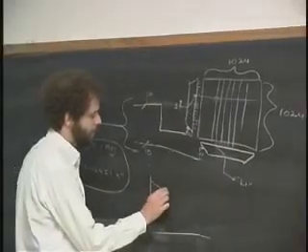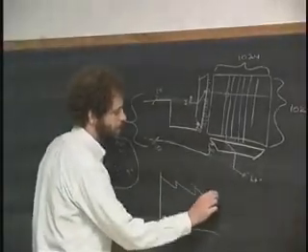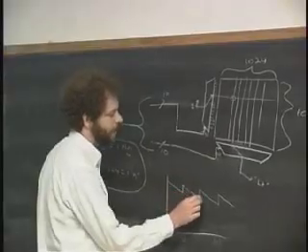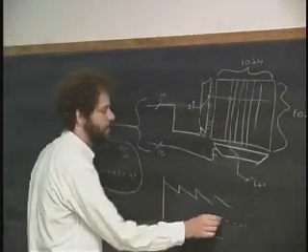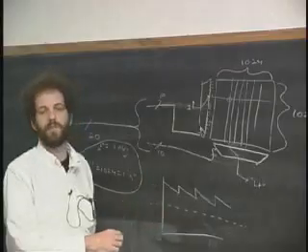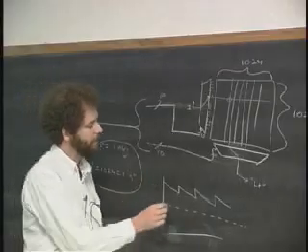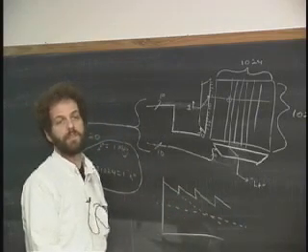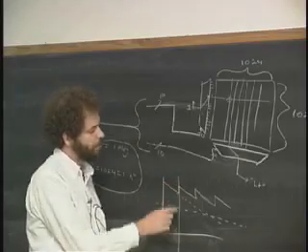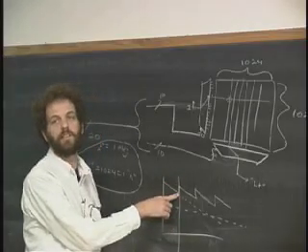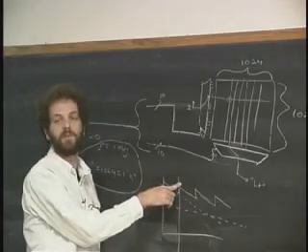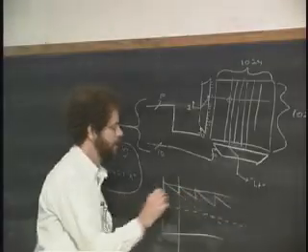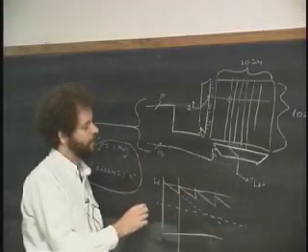So typically the charge inside of one of these capacitors, if it's being maintained at a high, kind of looks like this. So here's where we fill it up to, and then it leaks down. Fill it up, it leaks down. And here's the threshold that we use to determine is it a 1 or a 0. Now, if we're lazy, this will leak down past the threshold, and we won't know whether it was a 1 or a 0. But if every so often we go over to that thing and say, oh, let me check to see whether you're high or low, and then I'll write back with higher quality than I was willing to accept when I read, and you write back, this is a nice, strong, high voltage, then I'm okay.